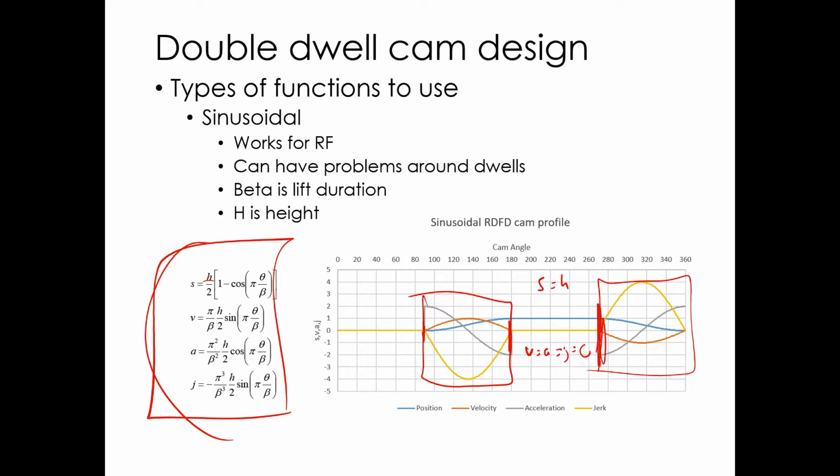And if you'll note, they're not just symmetric. They're not just these things run from theta equal 90 degrees down to 0. There's some minus signs involved, and I'll talk about how to apply that in a later slide. But the main thing to get is that these equations are only valid for the rise part of your CAM program. And everything else, all the dwells you have to put in and all the falls, you have to modify these equations a little bit to be able to use them. So that's the important thing to get.